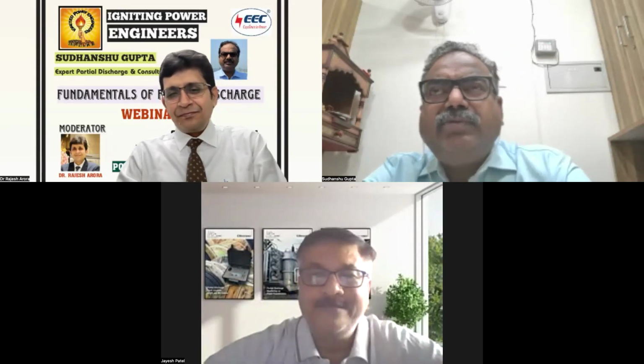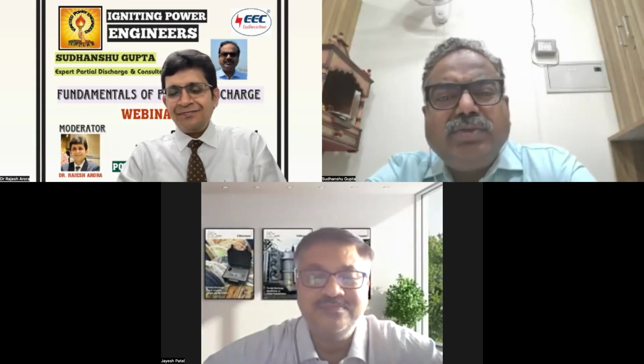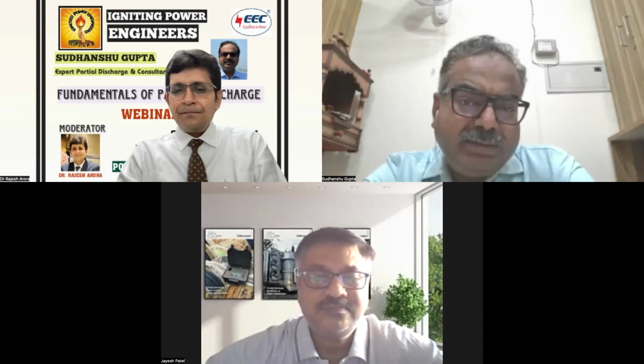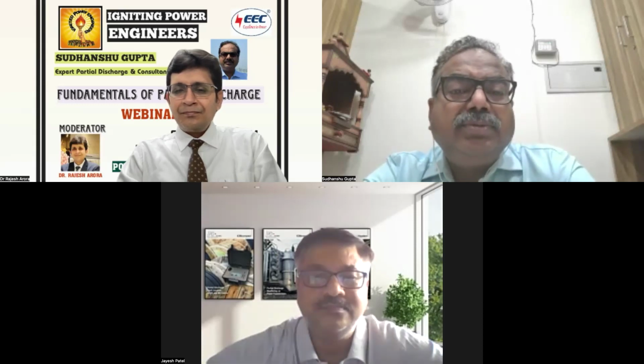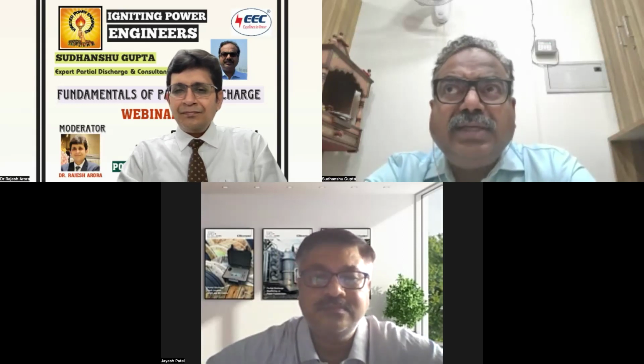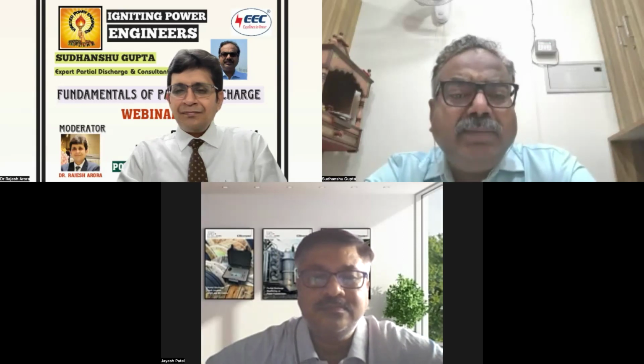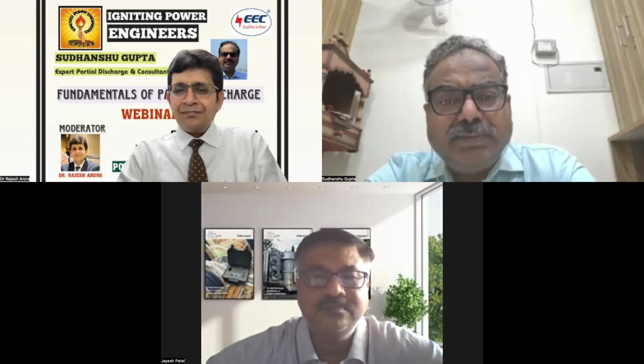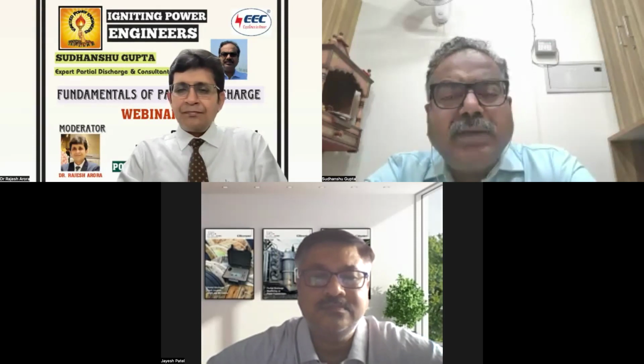Okay. First of all, your question was about IEC 60270 implementation at site. IEC 60270 at site most of the time leads to wrong results. I'll give you one example.